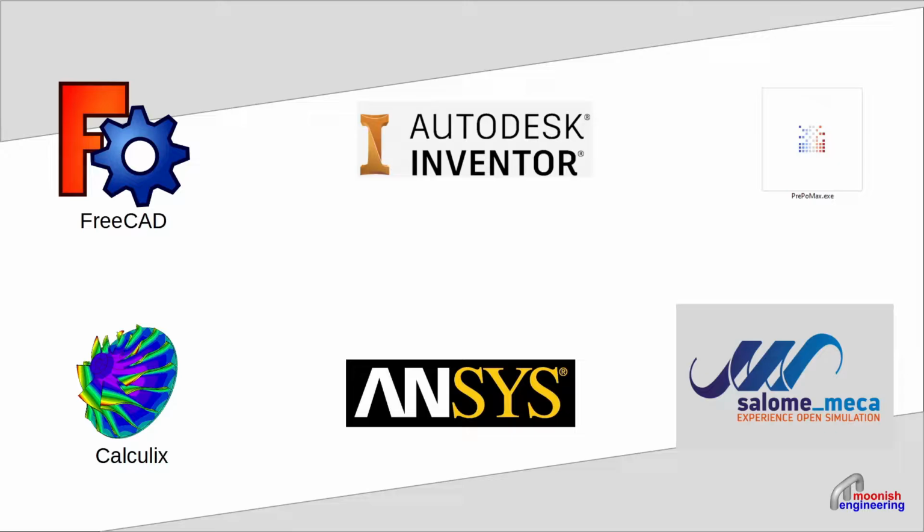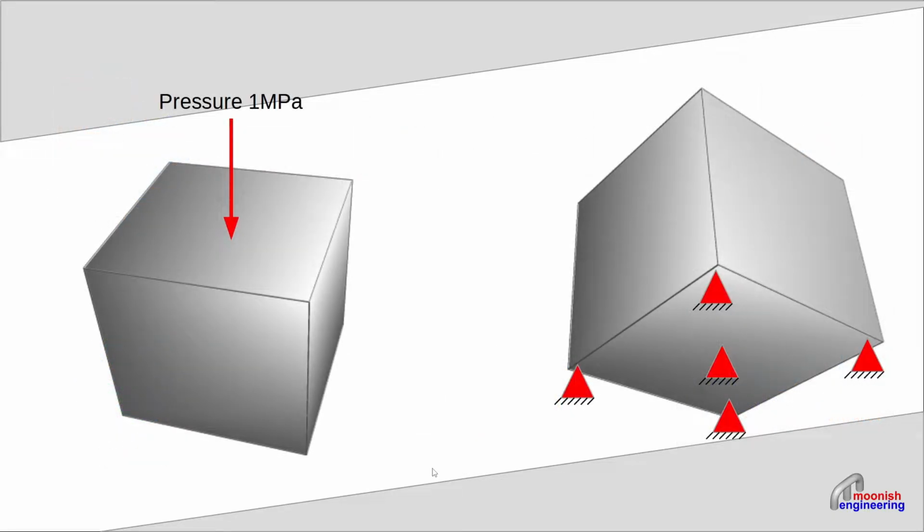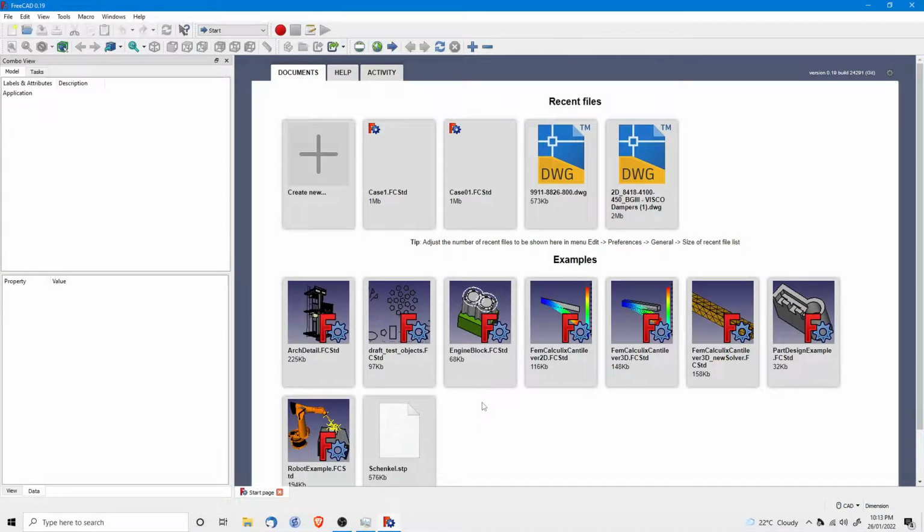All of these softwares will be used to conduct a finite element analysis of a cube. The length of the cube is 1 meter, width of the cube is 1 meter, and the height of the cube is 1 meter. So it's a 1 cubic meter cube. The pressure to be applied on the top face is 1 megapascal, and the bottom face will be constrained. There are a few different constraints that we'll be trying out in this series, so stay tuned.